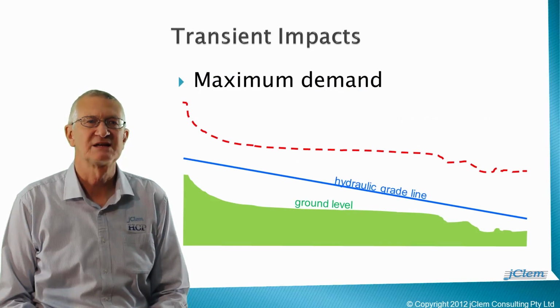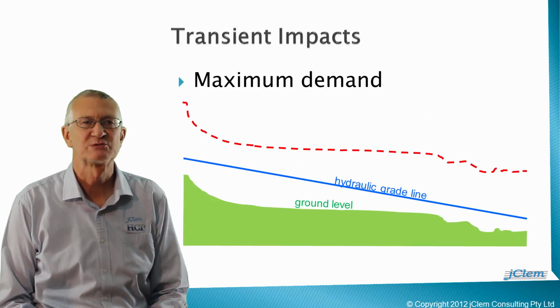When a power failure stops all pumps during maximum peak hour demand, the initial steady-state hydraulic grade lines are likely to be at their lowest levels. The initial hydraulic grade lines will be closer to the minimum head design limit, which is likely to be near ground level. Consequently, a pump stop scenario at maximum demand may generate the lowest heads in the system.